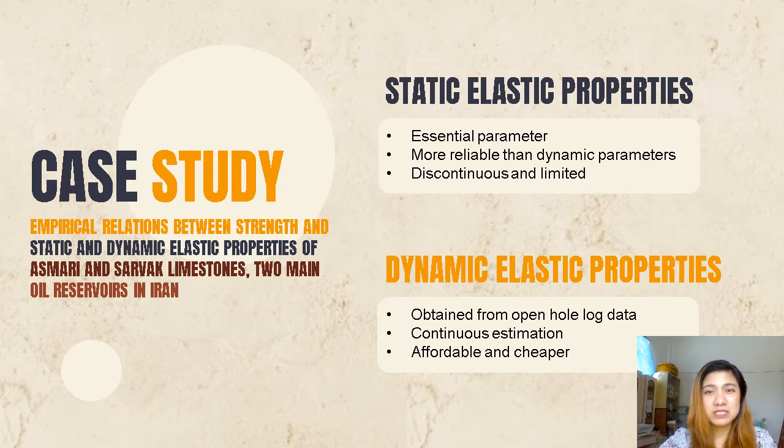Relatively, they observed that static Young modulus is 3 times smaller than dynamic Young modulus, which we can relate to my explanation previously. Also, they concluded that pores and cracks might have affected the static measurements, and yet static parameters are more realistic and widely used in geomechanical modeling.